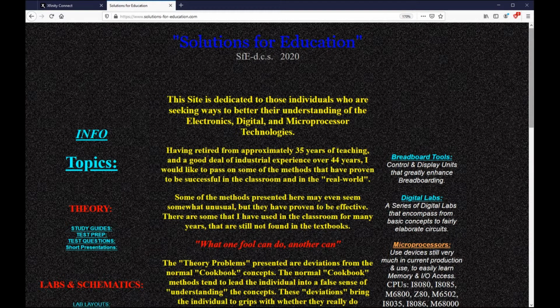This discipline has to do with current supply, and when I say current supply, it can be a controllable current. Notice that during this discussion, I will rarely talk about applied voltage. I'm only talking about current that you apply. For instance, who in their right mind would say, okay, put a 12-volt battery across a dead short? Well, somebody says, but I want to measure current through that dead short. Can you do that? The answer is yes, but to do that, you have to have a power source that supplies current. Don't think about voltage, think about the current.